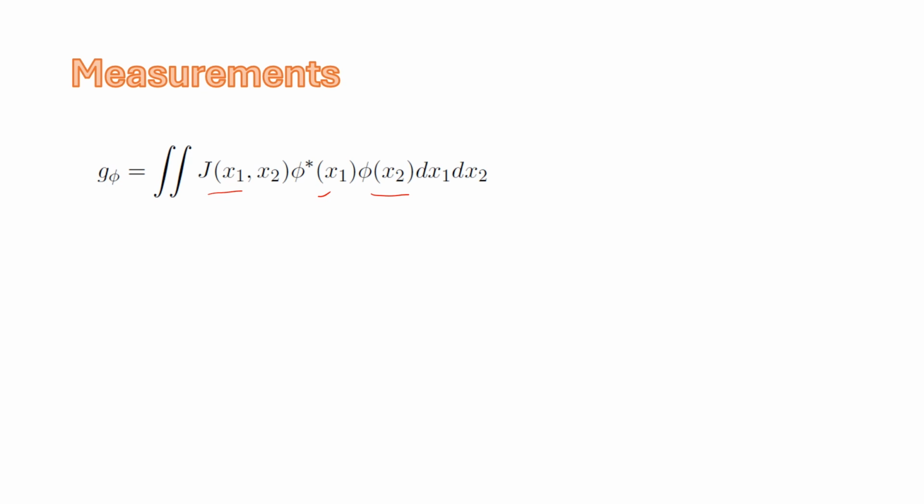Now, of course, we could represent phi as a vector projected onto the band-limited basis. The mode phi, the measurement mode, is not necessarily band-limited, but only the parts within the band of J would have a non-zero integral with respect to J, so we can project phi onto this sinc basis, sinc in this case being our one-dimensional impulse response, but of course in 2 dimensions we could use a basis function that fully described J in the 2 dimensions.